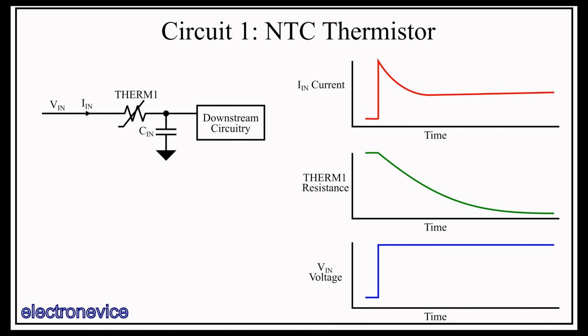During the initial phase, when the thermistor is heating up, the current flow is limited significantly, and the input capacitance is charged up slowly through this relatively high resistance. By the time the thermistor is hot enough to be low resistance, the capacitance is all charged up already, and the inrush phase is over.